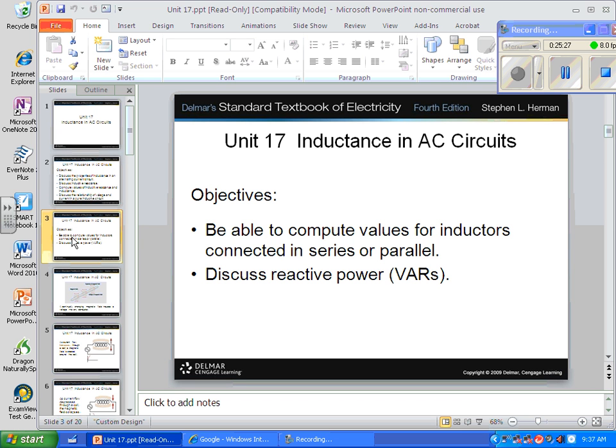Why would he call them rotating transformers? Because the rotating windings were interacting with the outer windings, so they were inductively coupled. And there was iron in this thing to make it work better. So his motor had a wound rotor. You guys now know what that means. It's got a winding in the rotor, and that winding reacted with the stator winding. That's why he called them rotating transformers.